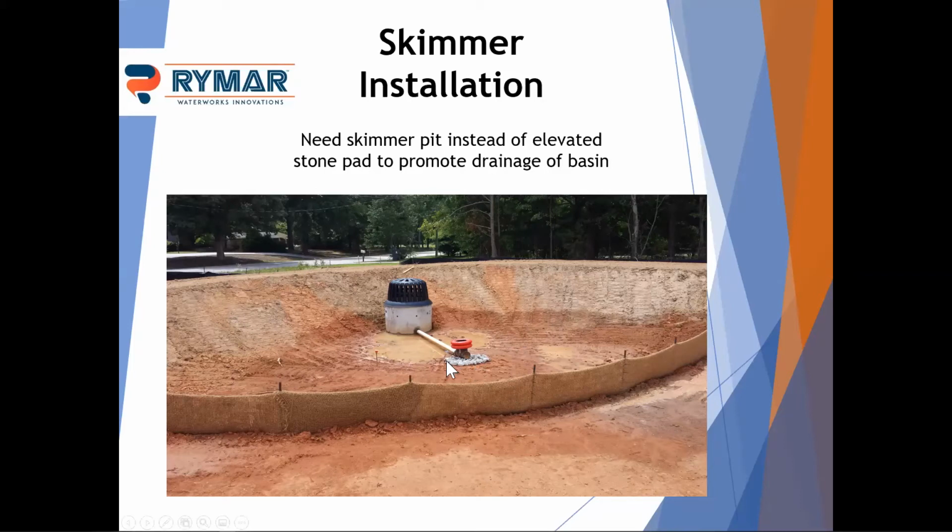So had they excavated this out a little bit more and set the stone down level, the skimmer would be sitting down another 6 or 8 inches, and this area would drain down to that skimmer pit and keep more of the bottom of the basin dry. So just one thing to look for.